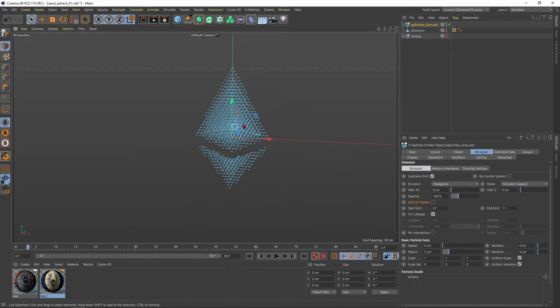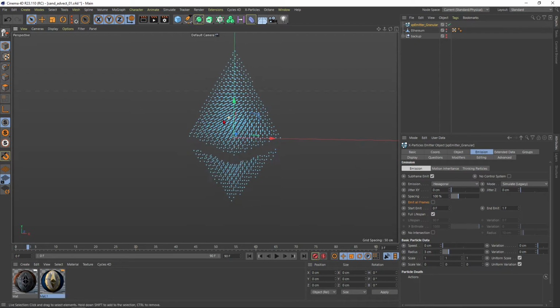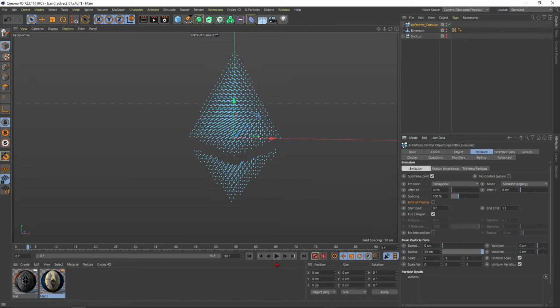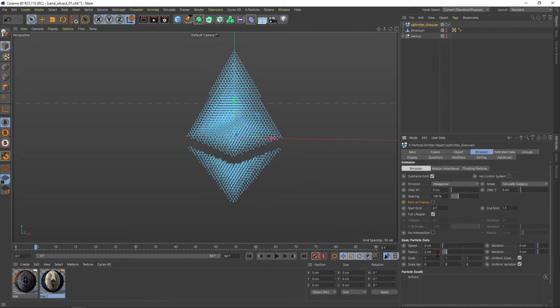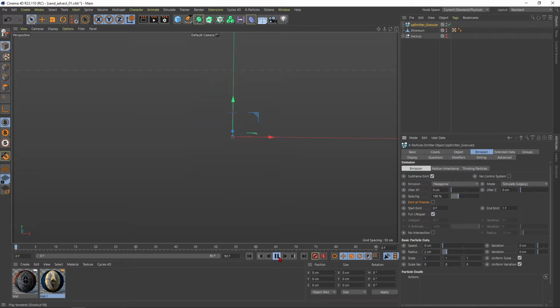All right, hexagonal is just a stacking pattern inside of a volume. So you just get this honeycomb pattern here. And with the particle radius, you can decide how many particles you want here. Okay, so if I put this one to 2, you can see this will get denser. If I put it to 1, it will get even more dense. So I guess when we want to make a final render, we just decrease this number. But for now, let's stick to something like 2, for example.